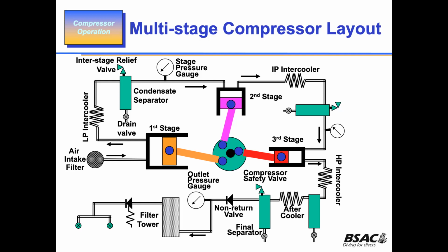So you try to condition gas to make sure that it's got a very low dew point and you've taken out as much of the liquid as you possibly can. So it's really a case of filtration. You want to make sure that none of the air that gets into your cylinder is wet, oily, or contains any other toxins that might be harmful for you to breathe.